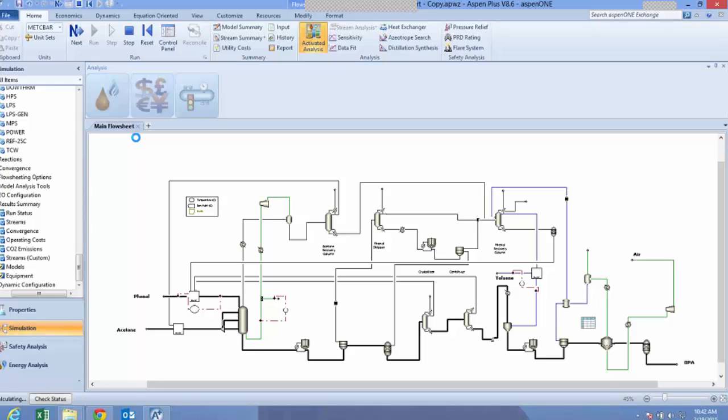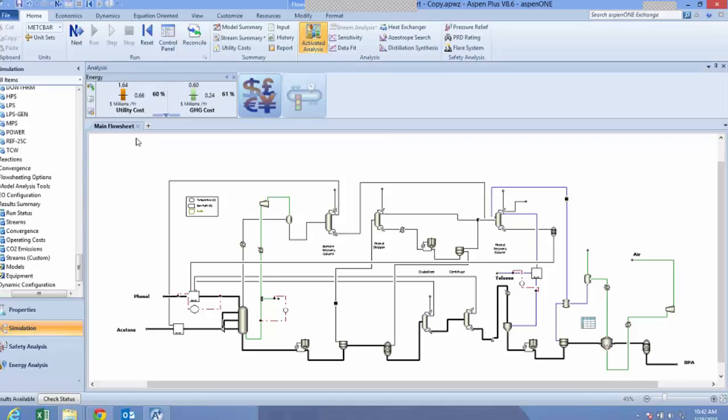Behind the scenes, again, it's taking my simulation results, it's sending it to Aspen Energy Analyzer, which was formerly called HXNet. And that's using a rigorous heat pinch analysis to evaluate the energy efficiency, what's called the target heat demand, and of course, it knows the actual heat demands from my model itself. So it shows that on these thermometers.